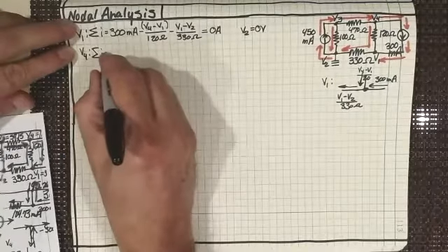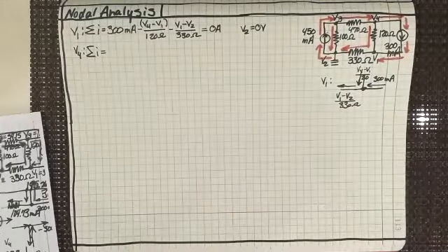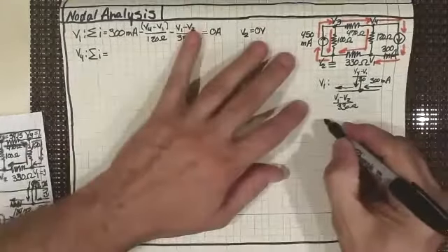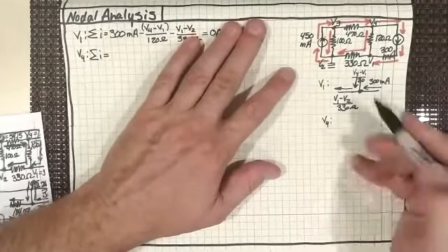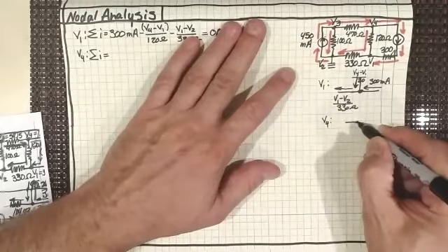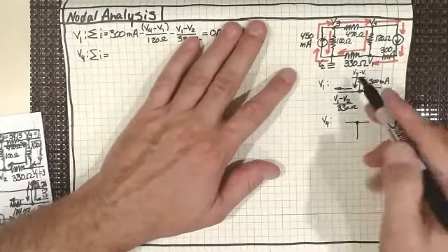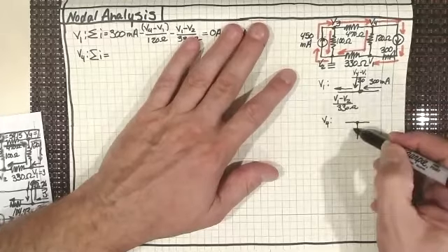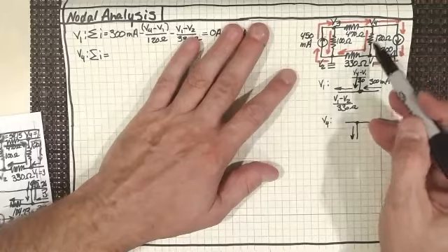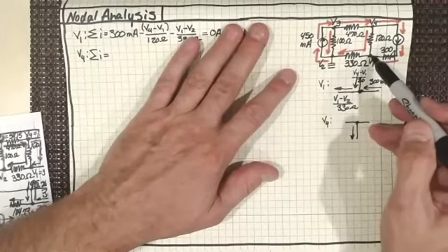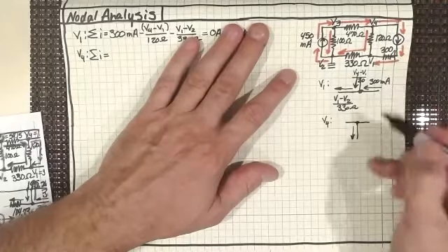At V4, when we sum all of the currents, let me draw V4 down here. V4 is this one up here, and so you can see that we've got current coming in, current going out, and then current going either up or down. Now, we've said that this is down, so we're going to assume here that it's going to be flowing out too, because there's no other place it can go to in here. If it's flowing down there, it has to be flowing in here. So here it has to be at V4, it's got to be flowing out from what we're assuming.